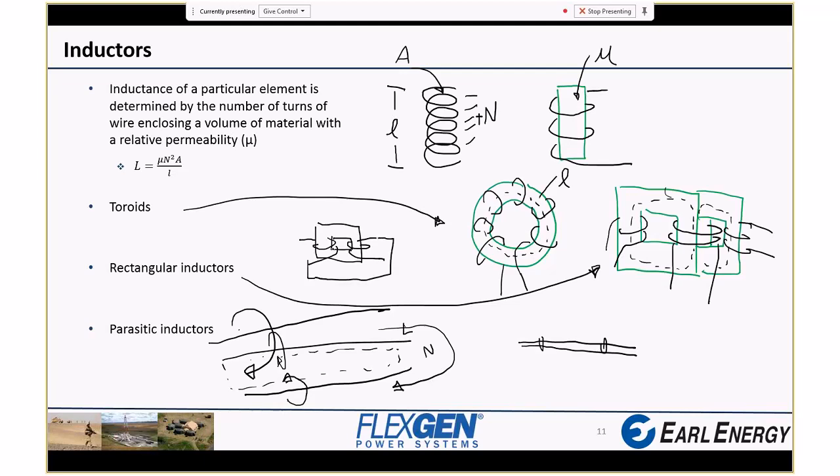So that just kind of makes it look a little more like a toroid. Windings connected in series on the same core is the very same thing as just putting more turns on the core. That just reminded me, another thing you can think about here. I mentioned before how you can work out the series and parallel combination of resistors and capacitors from this physical equation. You can do it for inductors as well. It's a little less obvious.